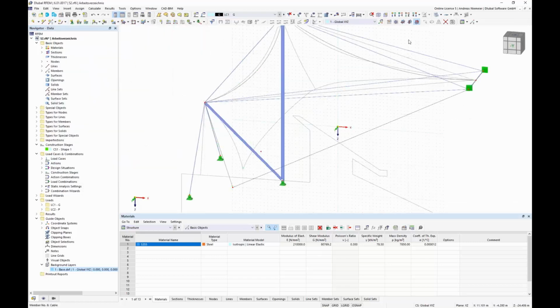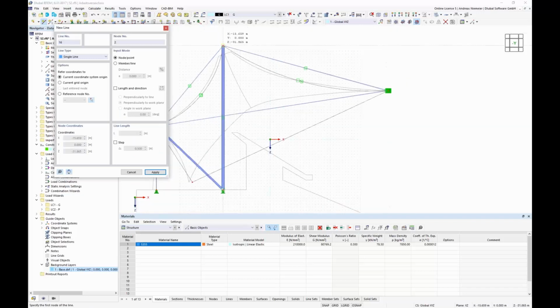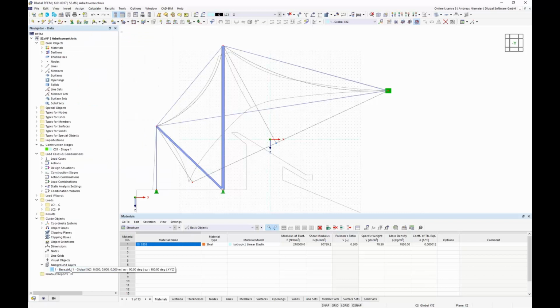Of course, it's not important if this line will match the DXF shape, because the form finding application itself will find the right place of structure. So it's not a target, it's only a, let's say, a tendence where it should go. And now we can, let's say, not completely, we need here a splice cable, so also define here a splice, and if we want to define it here on the perpendicular point, we can do like this. Now we can deactivate this shape.